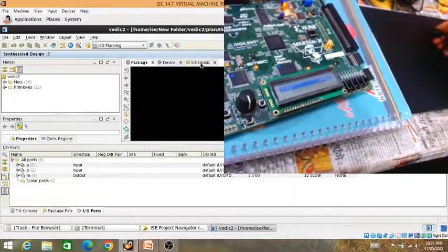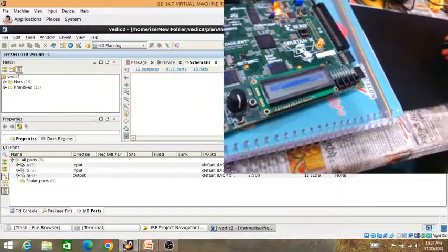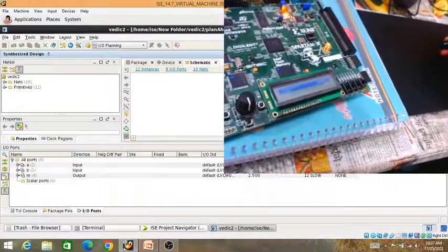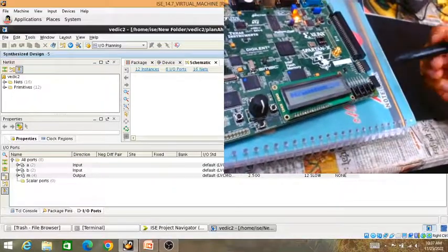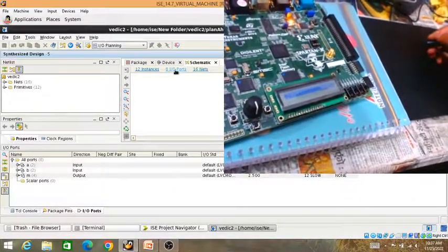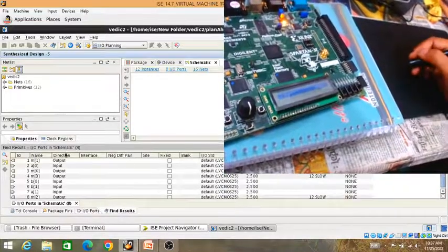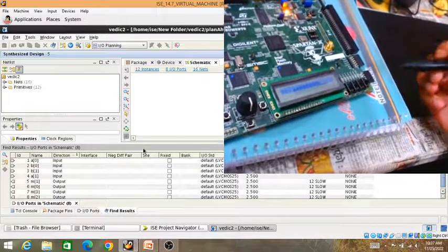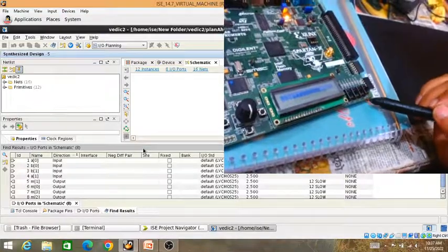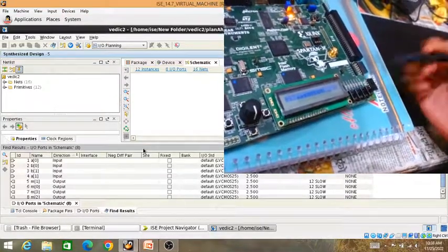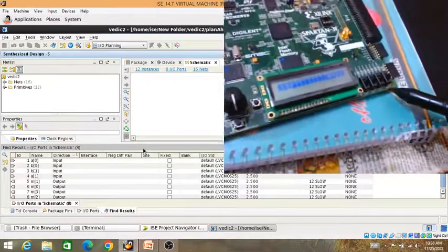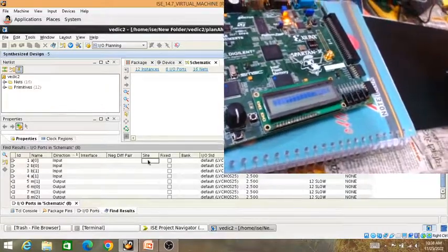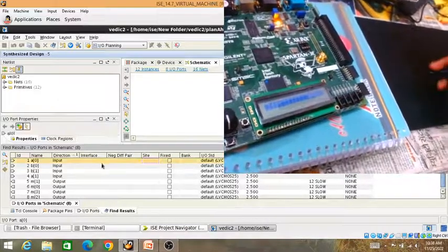Now click on schematic. We can see the LUT file here. So we have to define the input and output pins through which we can give input and take output. So click on IO port. Here we have to write the site name of input and output. Basically we have to give the pin name where we give input and the port name where we take output. So basically these are the input pins, like L11, L13, L14. So fill these pins into the site name.